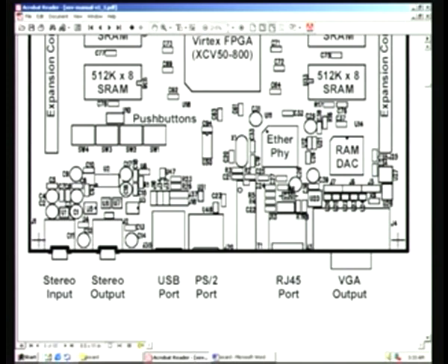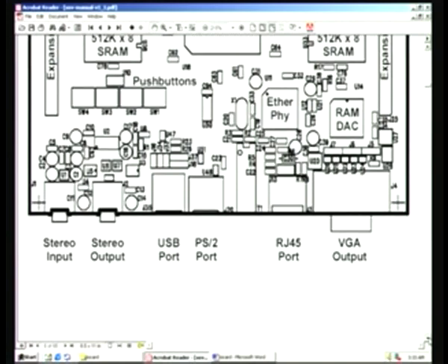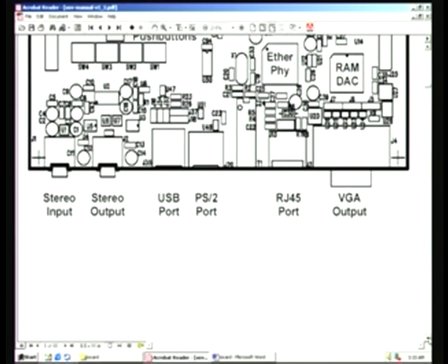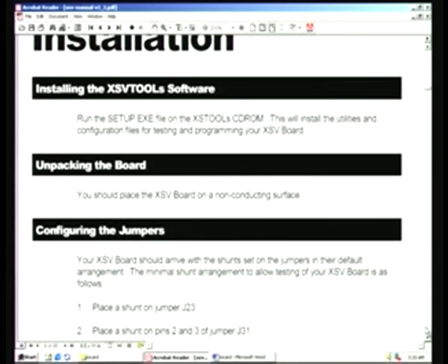and since only digitized signals are available here right onto the FPGA pins, you can do any processing that you wish, and you can have a USB port, which we have already seen, and it is capable of up to 12 Mbps. So you can establish a serial link in addition to this RS-232 serial link, which we have already seen, and that will go only for say 19,200 baud. Baud means bits per second, and this is the board feature that we have had a look at, and we will actually have a look at the board after a while.